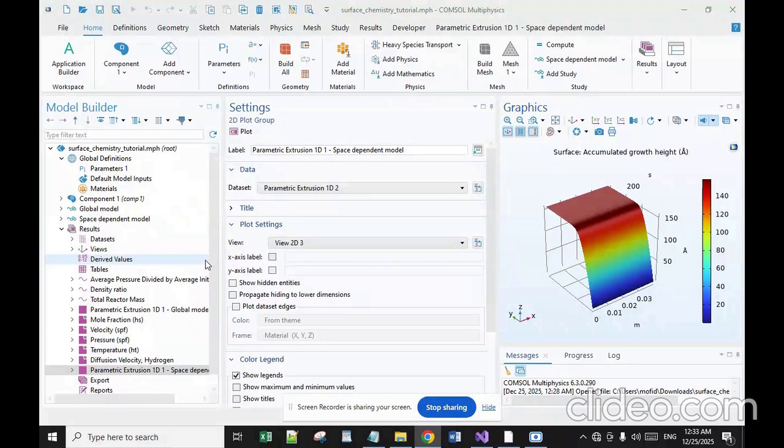And what are the challenges? The first challenge is hazardous byproducts, which requires careful handling of toxic or explosive waste gases. The next one is cost. Specialized equipment and high purity precursors can be expensive. The next challenge is thermal stress. High heat in thermal CVD can damage sensitive substrates.